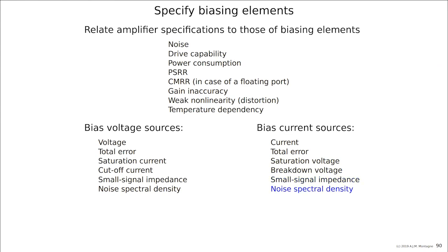And also here, if in our antenna amplifier we are going to implement a bias source, we can already in the small signal diagram insert, for example, a parallel connection of a resistor and a capacitor, because we know that most transistors that we are going to use have an output impedance, basically if you don't do any feedback around them, like a resistor in parallel with a capacitor.